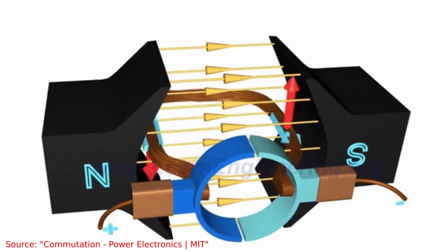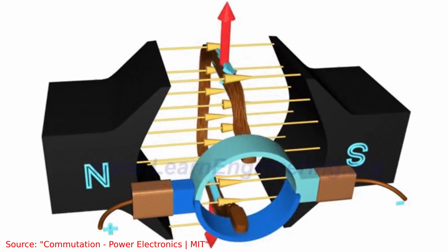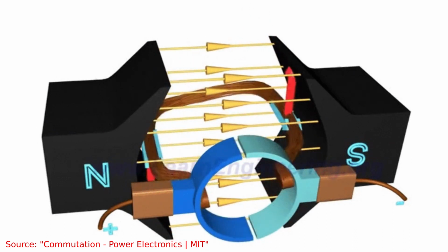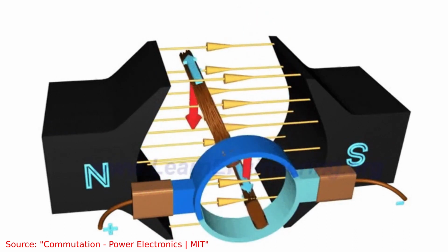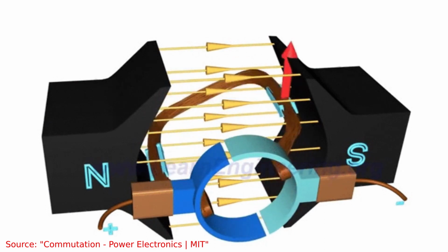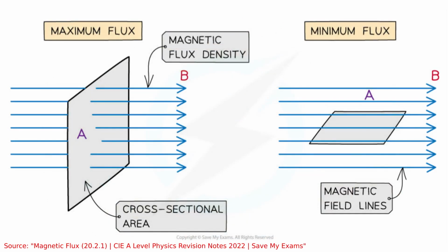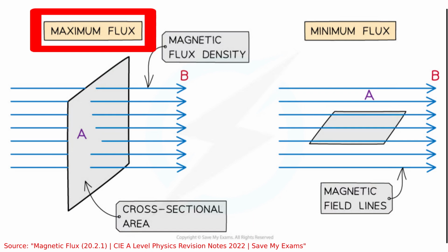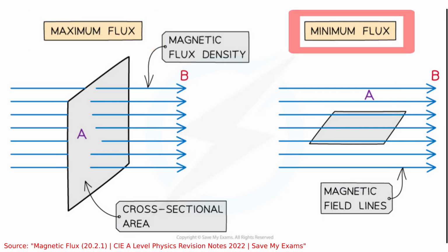As the rotor spins, there's a changing magnetic field passing through the windings. Let's imagine we only have one winding. We only care about the magnetic field which is perpendicular to the winding's closed surface. The sum of that magnetic field is called the magnetic flux. When the winding and the magnet are aligned, the magnetic flux is at its maximum, right? The magnetic field is completely perpendicular to the closed surface the winding creates. Once we start spinning the rotor, we see that the magnetic flux decreases until we reach a minimum when the magnetic field is parallel to the winding and is barely passing through it.